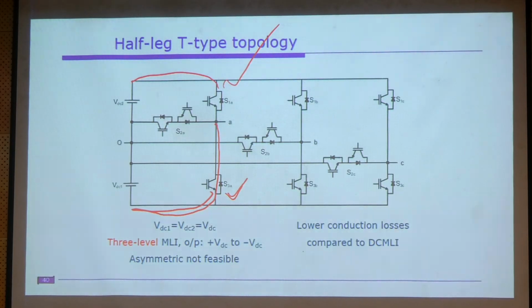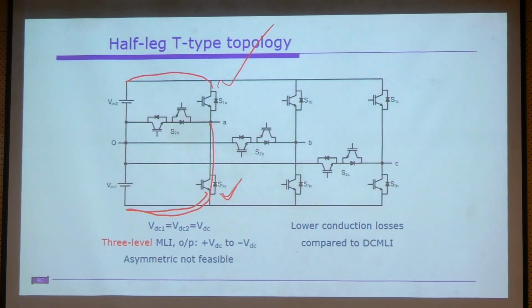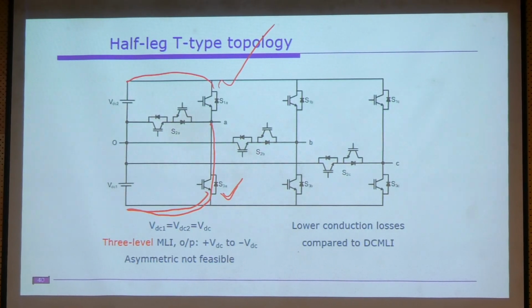And if it is a small circuit, this is fine. If it is a bigger circuit, you need to see all the possibilities. In some scenarios you will get VDC, in some 2 VDC, in some cases 3 VDC. Whatever the maximum is, that is what is supposed to be selected. Blocking voltage is the maximum, you know, the peak inverse voltage, right? Peak inverse voltage and blocking voltage are both the same.